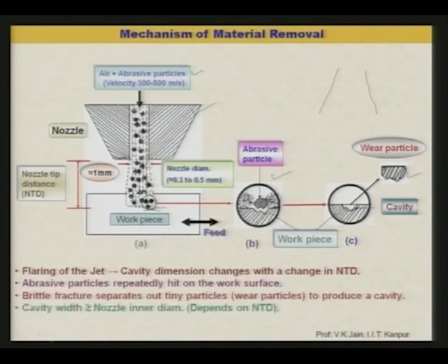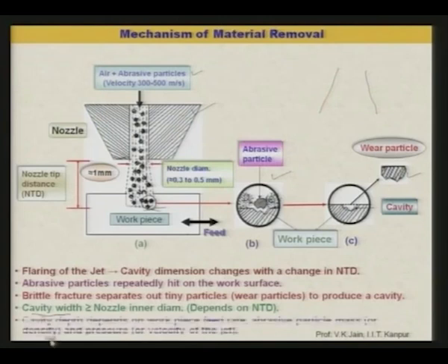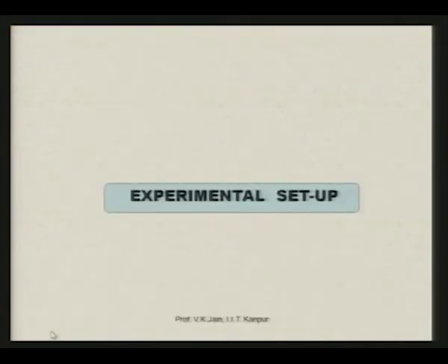Now, the cavity width is greater than or equal to nozzle inner diameter. What is the actual cavity width? It will depend upon the stand off distance or nozzle tip distance. Cavity depth depends on workpiece material, feed rate, abrasive particle mass and pressure also. Let us see the experimental setup for abrasive jet machining.